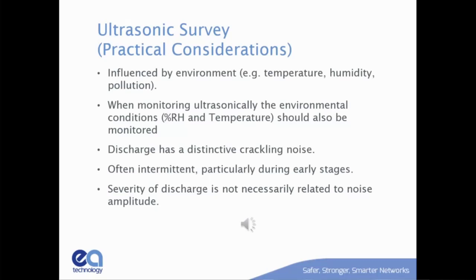Our instrument uses 6 dB as the transition point from where we say green to red. That doesn't mean that if it's 8, you need to panic, and if it's 5, you're fine. What it means is if it's 30, you got a real problem. If it's real borderline, you need to kind of watch it over time, or watch it over humidity.